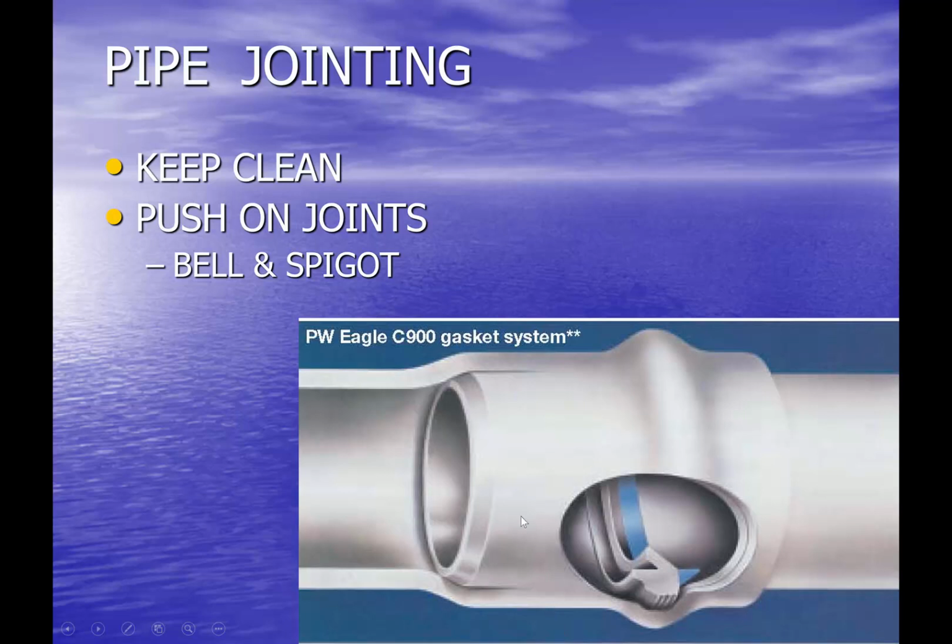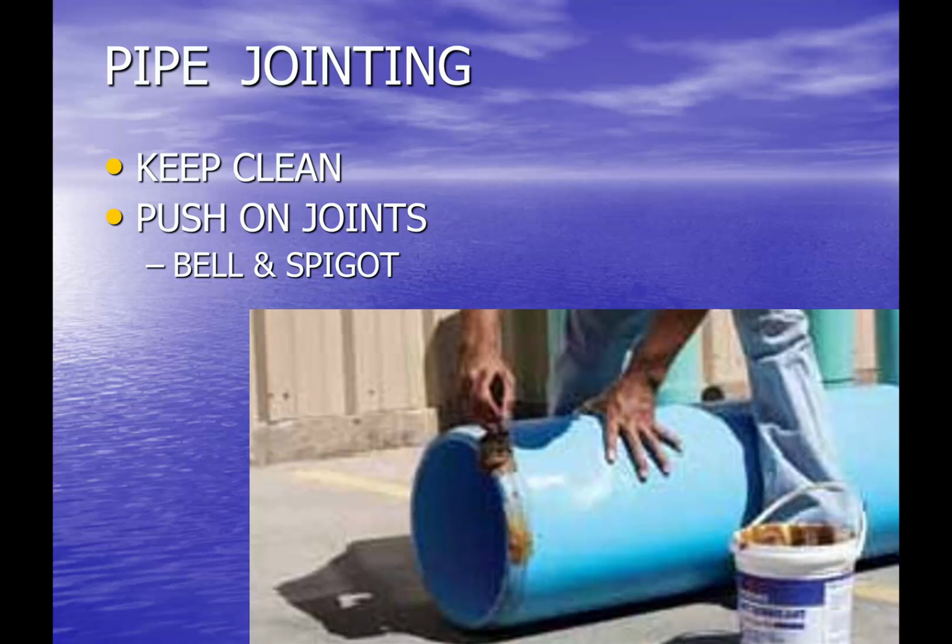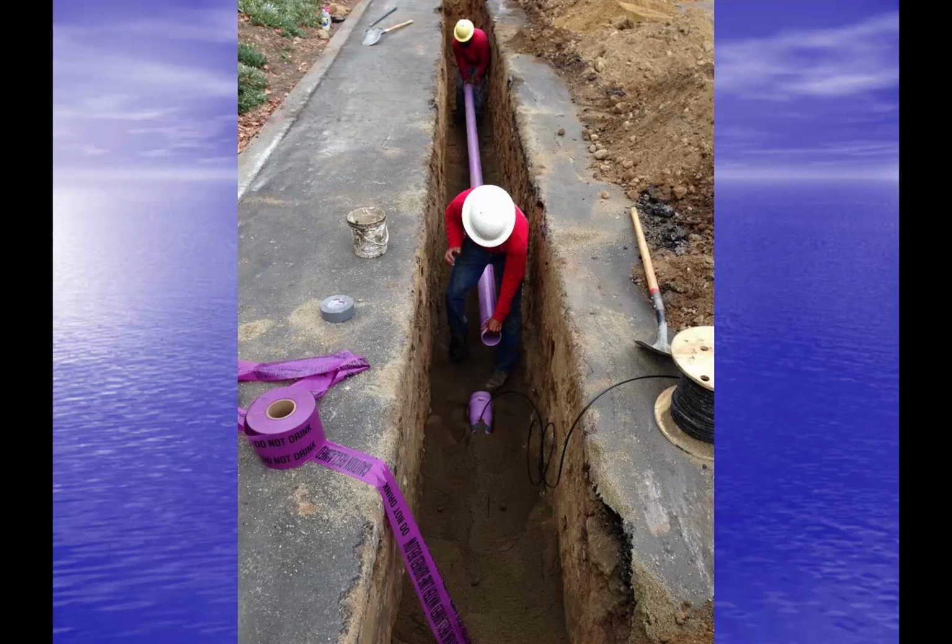And just as a reminder, the reason that we have this bevel is so that we can get the pipe past the gasket without doing any damage to it. It creates a narrower end of the pipe that can slide through the gasket, and then the barrel of the pipe can make it through because we've lubricated it with some sort of food grade grease that will allow the pipe to be relatively easily put together.